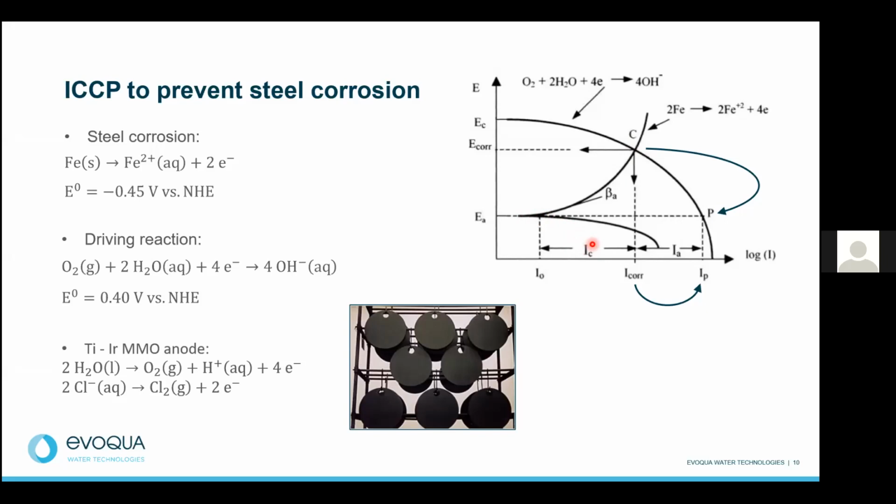Nothing happens anymore, and at that point, the structure is cathodically protected. To achieve this potential, you still need to have some kind of oxidation current to maintain this electrode, but instead of this oxidation current coming from iron, it is now coming from the titanium iridium MMO. And all the current is localized on this MMO. So the MMO basically takes over the role of oxidation sink from the iron, protecting the structure.